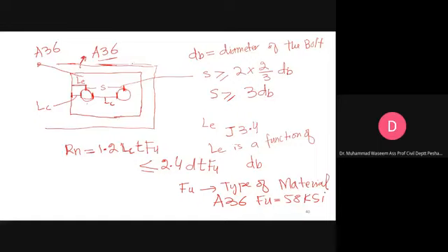Now, you have to apply this equation here, and also here. This bolt will exert pressure to this side if the load is acting in this direction, and this will also be exerting pressure. So you have to evaluate bearing strength here and here using this equation. You have to carry out all these operations for this plate.